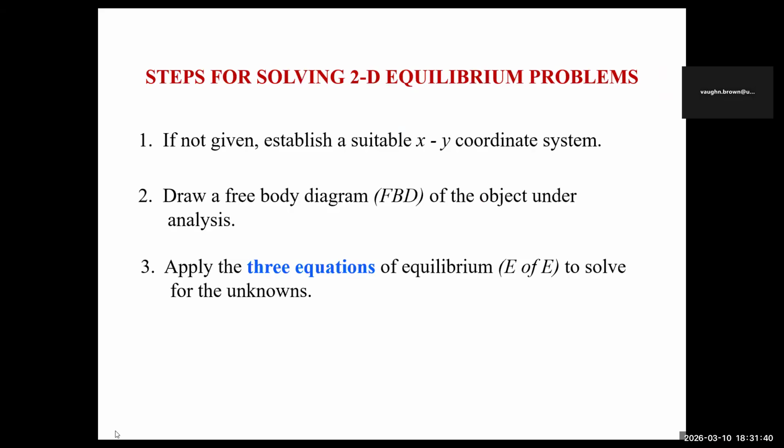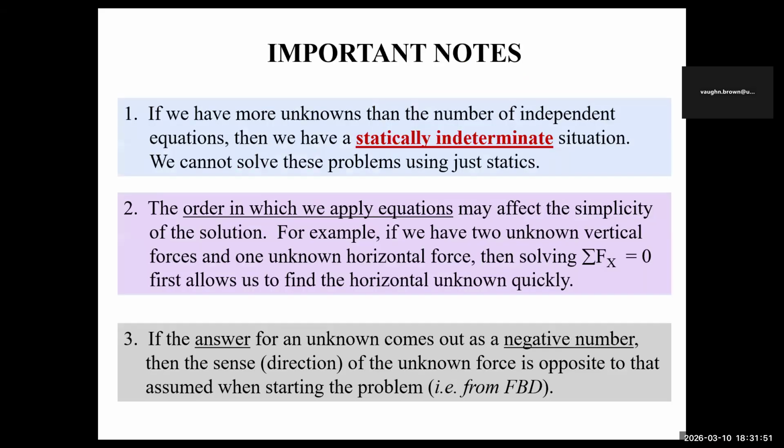And so the method of solving these problems is to establish some sort of X and Y coordinate system, draw a free body diagram, and use your three equilibrium equations for your unknowns, right?